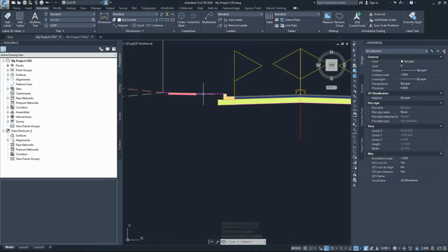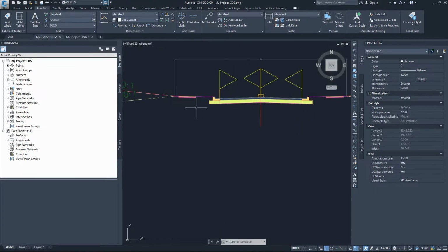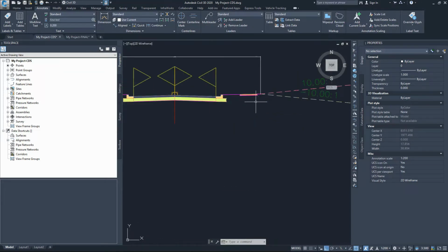We have to take from each side 2.5 meters. I've got 1.5 here. We can get rid of that boulevard area. We've got that 300 we can get rid of, and that 1500 wide sidewalk, we can make it 1 meter sidewalk. So we already got 1.5 meters plus 300, that's 1.8. We can take 500 of the sidewalk, that will make it 2.3. We still need another 200. We can take it from the lane. We can make the lane 3.4 rather than 3.6. So let's do that.